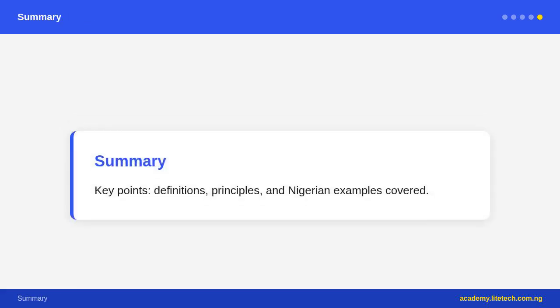wall is perfectly vertical. Damp-proof course, or DPC, is a waterproof layer built into walls close to ground level to prevent moisture from rising up from the ground into the wall above, a problem called rising damp. In Nigerian buildings, the DPC is typically a layer of bitumen-coated felt or 2 courses of engineering bricks laid at floor level, before wall construction continues above.